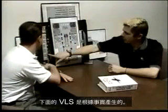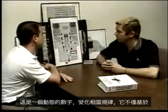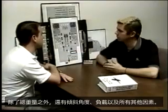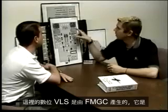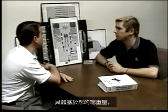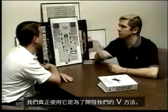Okay, the VLS down here is generated by the FACs. It's a dynamic number which changes quite regularly, and it's based not only on gross weight, but angle of bank, load, and all these other factors. The number up here, VLS, is generated from the FMGC and is based specifically on your gross weight. And all we really use this for is to develop what our V approach is going to be.